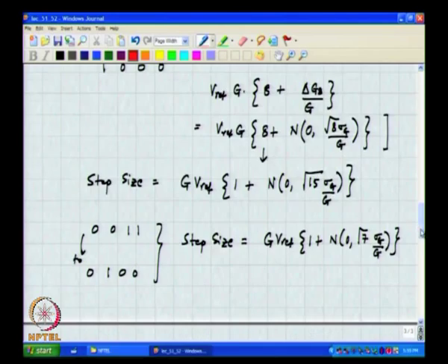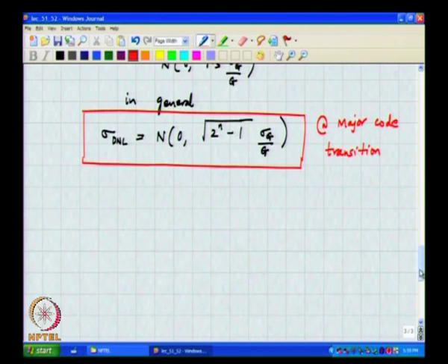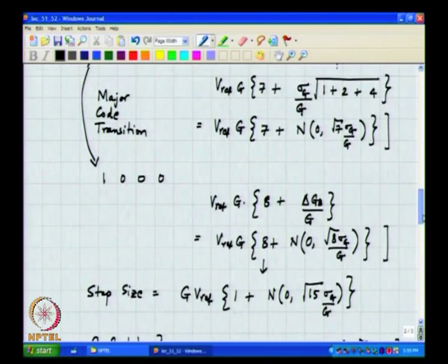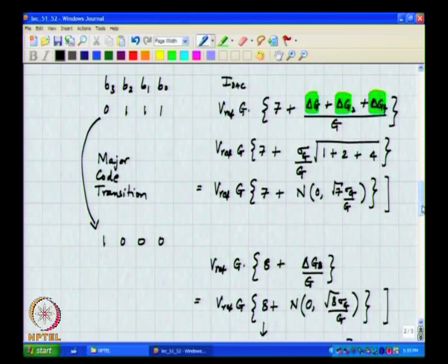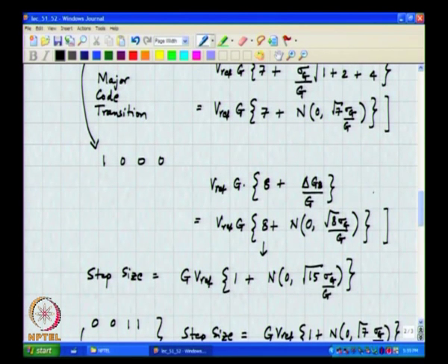So, what is the INL at the mid code? At mid code what is the output? Let us say this is what we define as mid code when it is 8. So, clearly the ideal output should have been this.